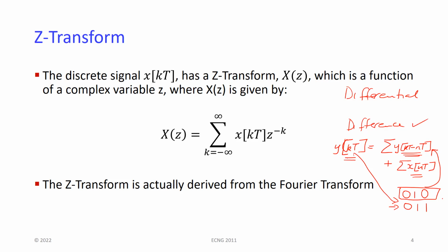And to solve a difference equation, we needed a different tool, which is where the Z transform came about. It is specifically designed to work with discrete, sampled information, and the form of it in general looks like this. It's a power series, so the Z transform of a sequence of values is simply that multiplied by this complex variable Z to the power minus K, counting from minus infinity to infinity. This is the two-sided transform.